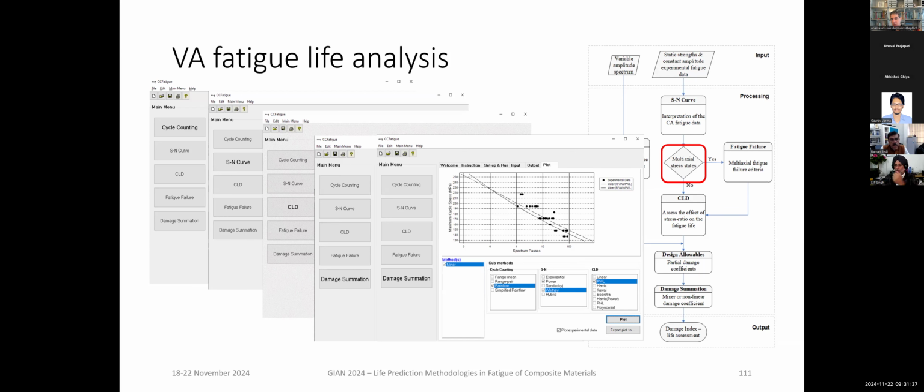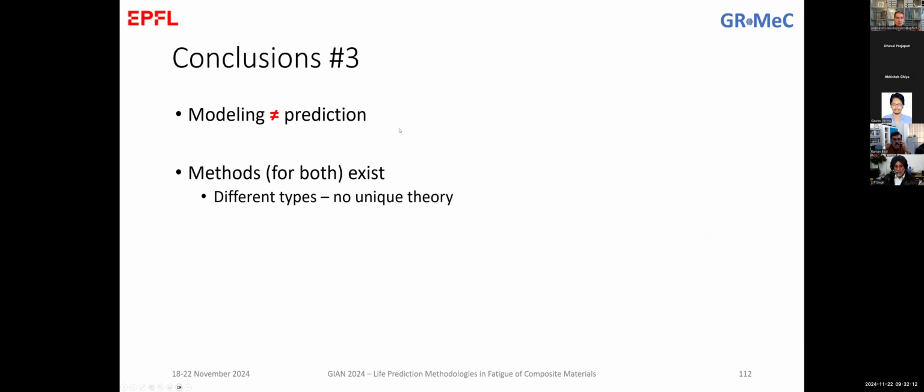But experience with a lot of materials shows that if you mix these blocks, with high, low, low, high, and so on, and you try to see which damage rule fits the material behavior better in this case, then we've seen that Miner's rule works quite well, because actually the sequence effect is dissolved in a lot of different changes that we do one after the other.